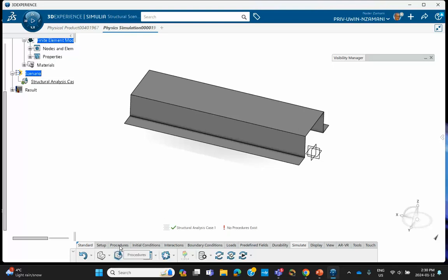So now we're going to go to procedure, static step. Now, if you're going to do a linear static step, when I do this, I have to go and uncheck the NL geom. And if that is the case, then instead of doing this, why don't we do the linear perturbation step, static perturbation step? Because that's the same thing. This is the same as that when there are no nonlinearities, okay? So I'll go to static perturbation step.